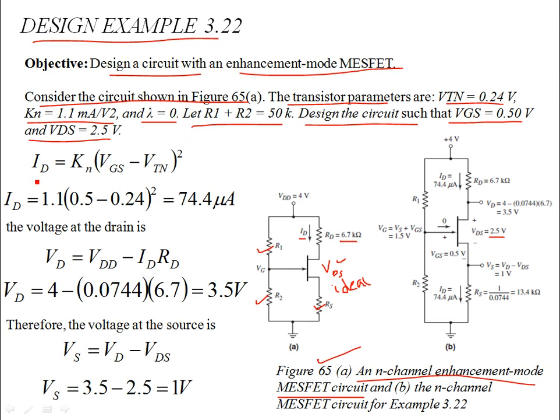For MESFET, the saturation current and voltage relationships, ID and VGS, are very similar to what we have in MOSFETs. The only difference in MESFET is that their VGS will be held to only a few tenths of volts. Other than that, as far as DC analysis is concerned, it's quite similar to the MOSFETs we have discussed in much detail.